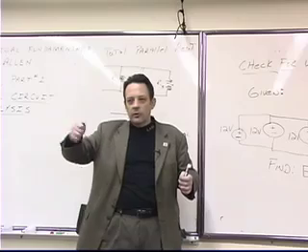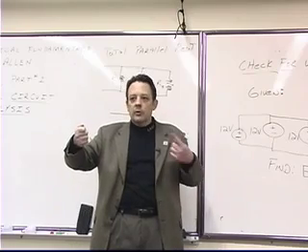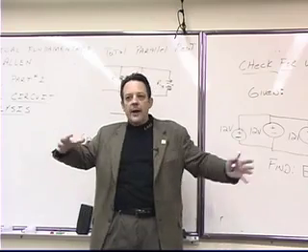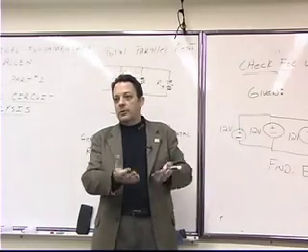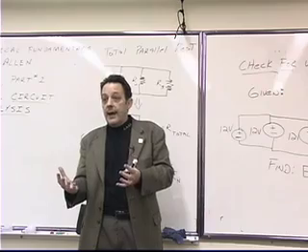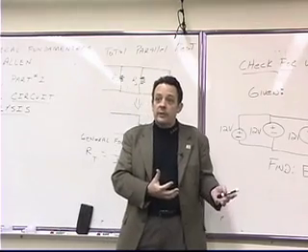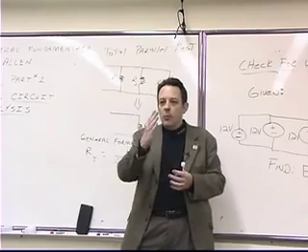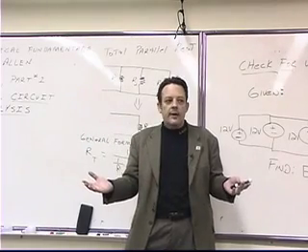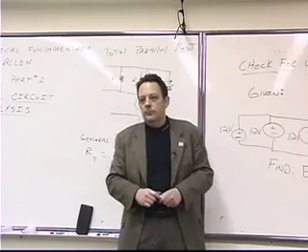Because when I turn the key for the starter motor to turn over, all 4 batteries are going to be pumping current if it needs to draw that much current. So if the cold cranking amp requirement is, let's say, 2,000 amps, then I'm going to have it if I've got 4 batteries. If I only have 1 battery, I might only have 800 cold cranking amps.